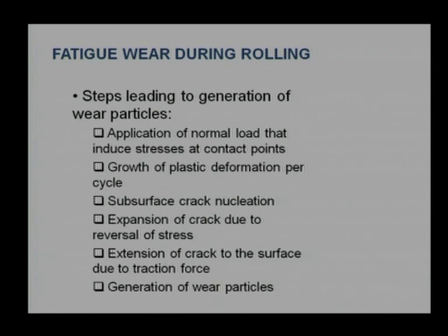So, what are the possibilities? The steps which are leading to the fatigue wear: first, we are applying a normal load that induces very high stress at the contact points. Believe me, contact stresses in bearings are almost 2 to 3 gigapascal, which is very difficult to imagine. We say steel has only 560 megapascal as a strength, how can it sustain 2 gigapascal? That is 3 times. The factor of that is just 0.3, and still the bearing can show a number of cycles.